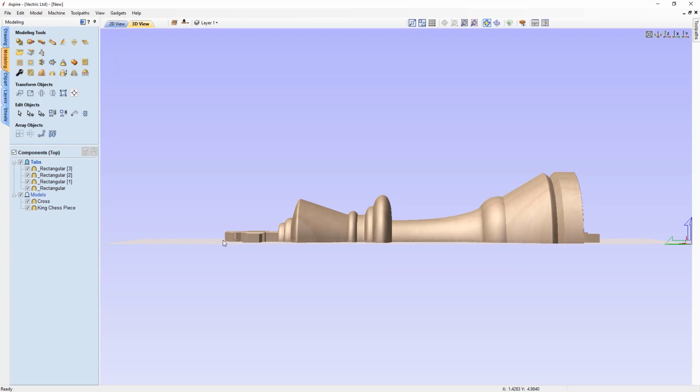To do that, we are going to set up a new level. We're going to put on that level a 0 plane, and we are going to give that a negative base height in order to drop it down so that we can make the tool go past the edge of our model. We're going to call that distance the overcut distance to that 0 plane, which will now be called our limiting plane, and stop it there.